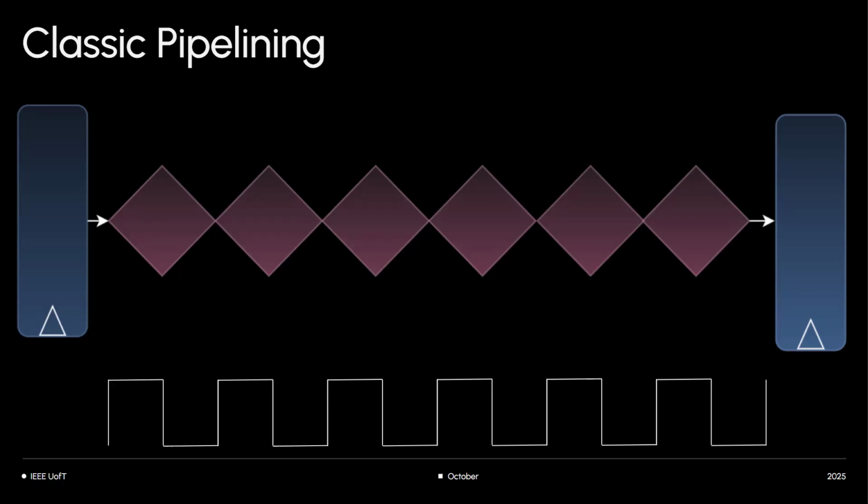So guys, for the biggest hitter, like how we always do, let's do a little bit of debrief on the engineering problem that we solved right now. In the first case, you saw a synchronous circuit, right? Because you could only move when the clock ticked. And the period of the clock, the length of each cycle, had to accommodate the worst case delay, right?